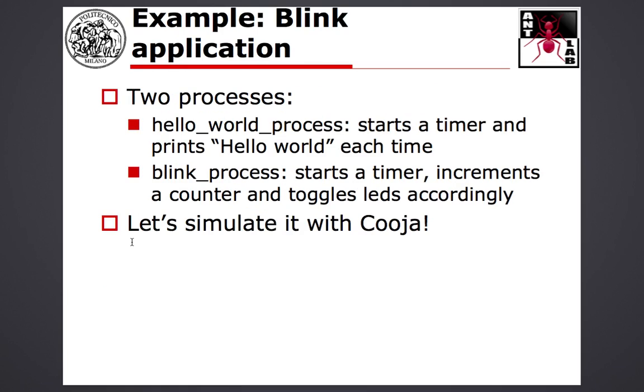Okay, now let's see another application which is a little bit more interesting, and it basically does the same work that the Blink application in TinyOS did. So we have a timer which fires and triggers the switching of LEDs. And in this case, we will use two different processes. So we will have a look at how we can manage two processes in one single application. And we will use a slightly modified version of this Hello World application that we have just seen, which basically starts a timer, and each time the timer fires, it prints Hello World.